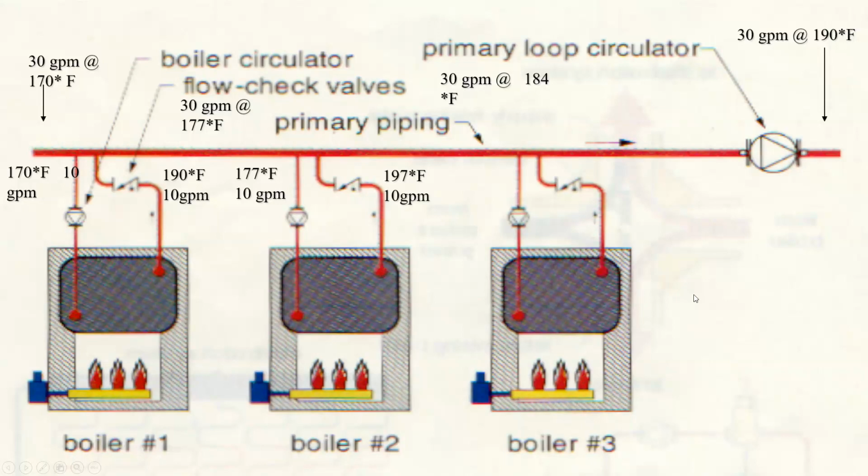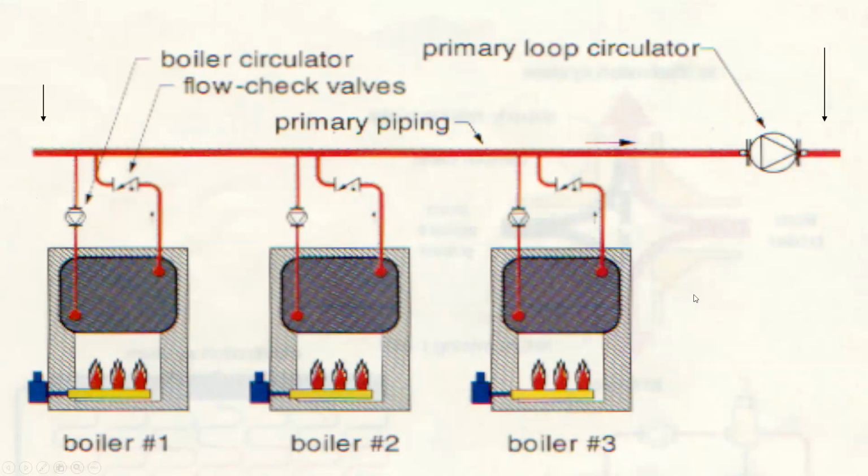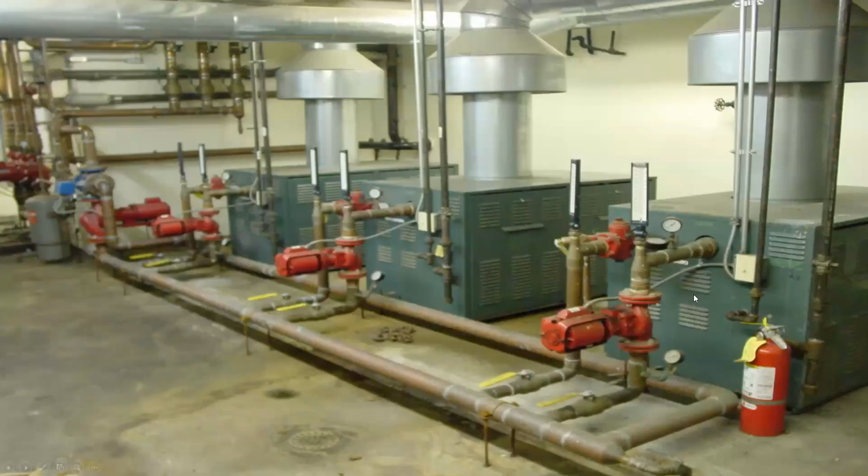So then I finally kick on the last boiler, and now my inlet temperature is 184. What's my outlet temperature? What should it be? If I'm adding that 100,000 at 10 GPM, 20-degree temperature rise, it's coming out 204. Now what I've done is I've taken each boiler, changed its efficiencies, and I'm elevating the inlet temperature to the next one, to the next one. So it's one pipe, primary, secondary, just like this drawing showed, right here. But there's some downside to that design.